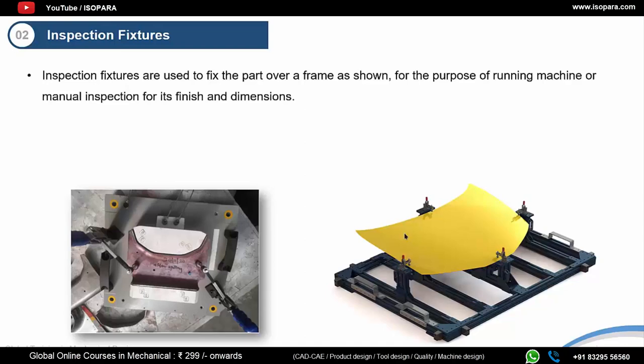Check gauges are another form of inspection fixture used to quickly and accurately determine if the parts are satisfying the basic tolerances. Now if the part fits into the gauge, the part is within the specification. So these gauges are basically a go and no-go type, or you can say like a vernier caliper, or a device with a needle here and a screen here which displays the tolerance. It will just give you the measure of the surface. You just place it at these locations, and the tolerance will be shown on this screen.